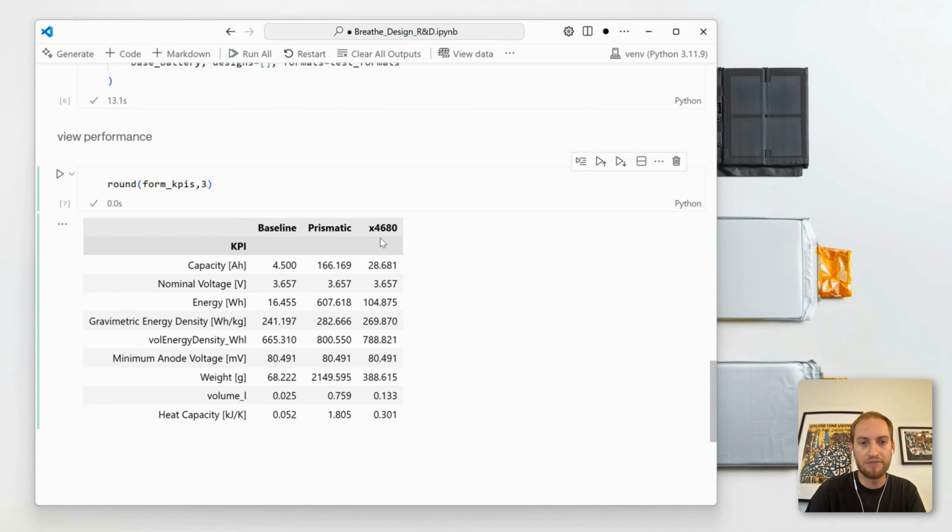And just like that, I've turned the moly cell P45B into a large form factor prismatic cell and a 4680. And so with the exact same chemistry, I can see what performance differences I get. You can see, for example, the energy density is quite a lot higher. And this could be really interesting in terms of maybe it would be worth taking the jump there and changing. I can see the predicted mass, so this might be interesting when I think about my application.